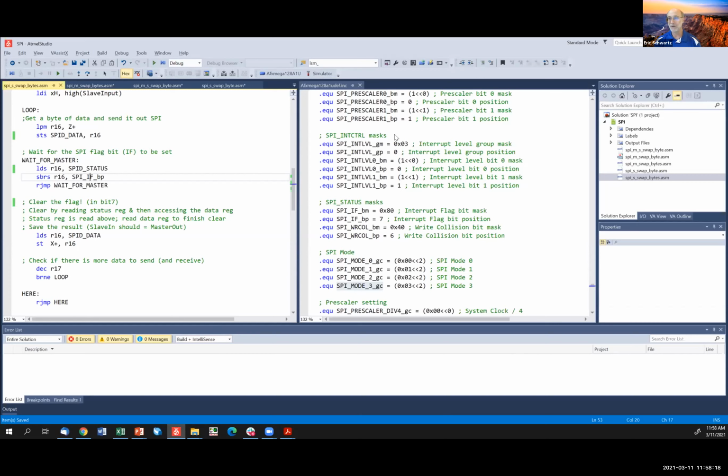And what you have to do in the lab is interface with the accelerometers on the IMU. What you can do then is know if your board is level, because basically what it's going to show you is how it accelerates. And if you've had physics, you know that acceleration due to gravity looks just like acceleration. And so if the board is like this, there's going to be a vector pointing in the direction of gravity acceleration, down. And if it's just sitting on a table and the table's not moving, accelerations in this direction and this direction will be 0. So you can know if your table is level.